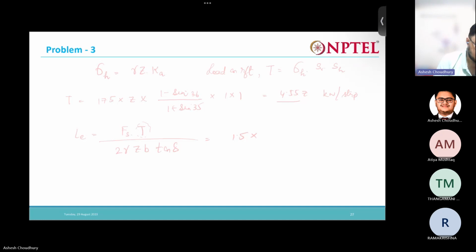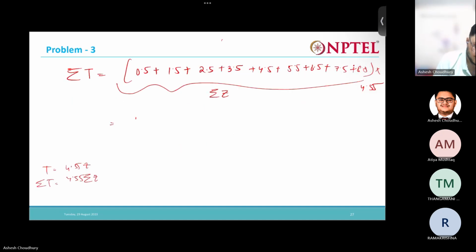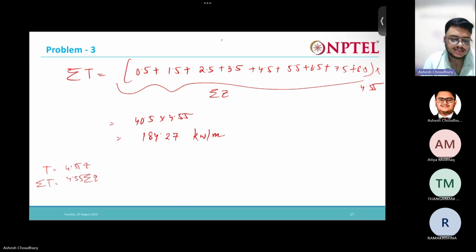So 0.5 plus 1.5 plus 2.5 plus 3.5 plus 4.5 plus 5.5 plus 6.5 plus 7.5 plus 8.5, times 4.55. 40.5 into 4.55, 184.27 kilonewton.